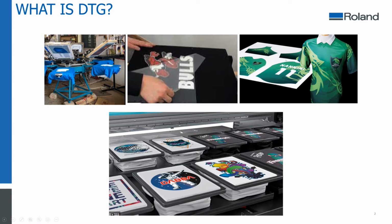Dye sublimation is a digital process using a transfer paper, then heat and pressure to transfer the ink gas onto a fabric. The quality is good and the results are very hard wearing, but dye sub has its limitations when it comes to garments. The ink is only compatible with polyester fabrics, and you cannot sublimate onto colored fabrics.